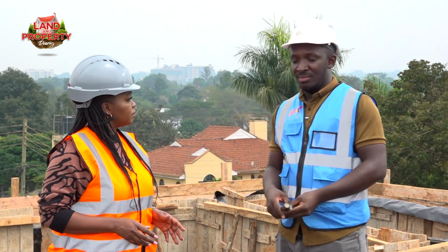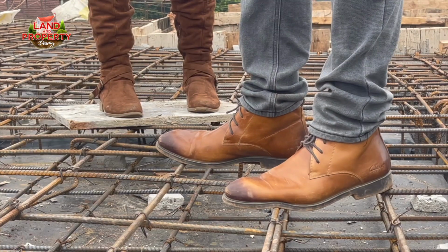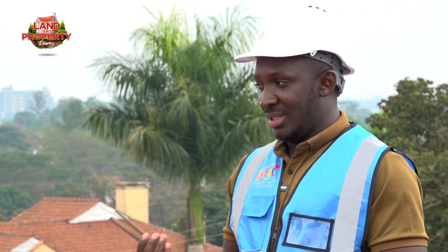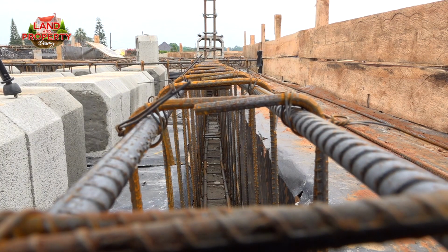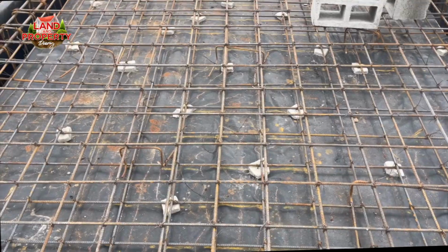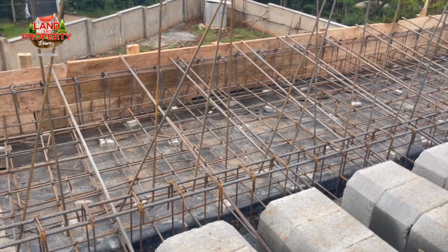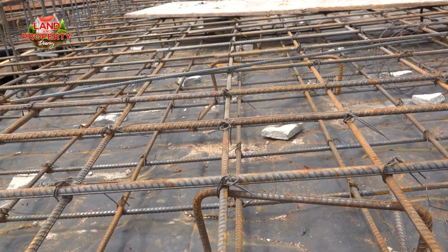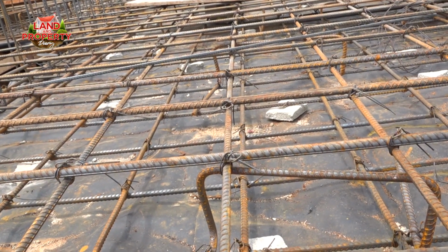When it comes to reinforcement steel, I think mostly people go for the cheap rebars. There are reinforcements which do not meet the standards but are there in the market. Okay. That is one mistake, the quality of the steel. The other mistake is placing the reinforcement rebar and not following the structural design. Also, there is something we call overlaps. They are not doing overlaps the way they are supposed to be done. Yeah. And also going for local fundis to guide them instead of using professionals. So if you use professionals, it's going to be cheaper on your side, because maybe the building may not fail, and also you might not use a lot of money in the project.